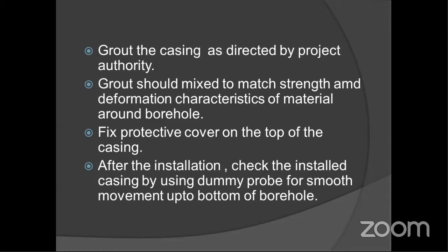To resist this, we can generally fill water inside the plastic pipe, so that the weight of the pipe will increase, and it will counter the buoyancy force. Or we have to put the couplers, which should be held by some weight, or we should put some pins, and those pins are going to hold that PVC pipe.